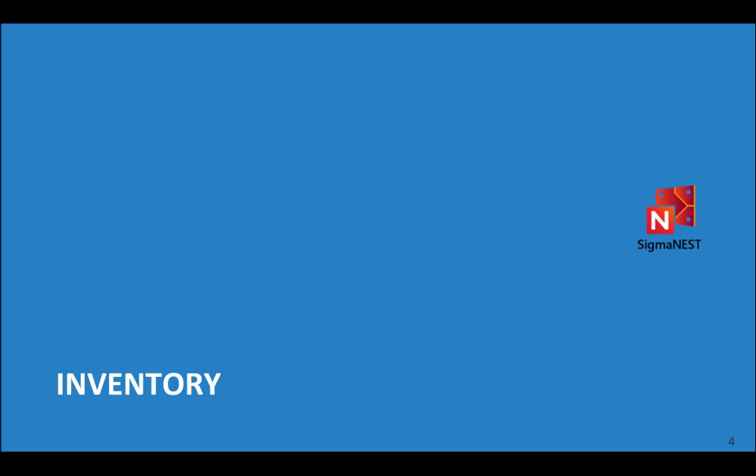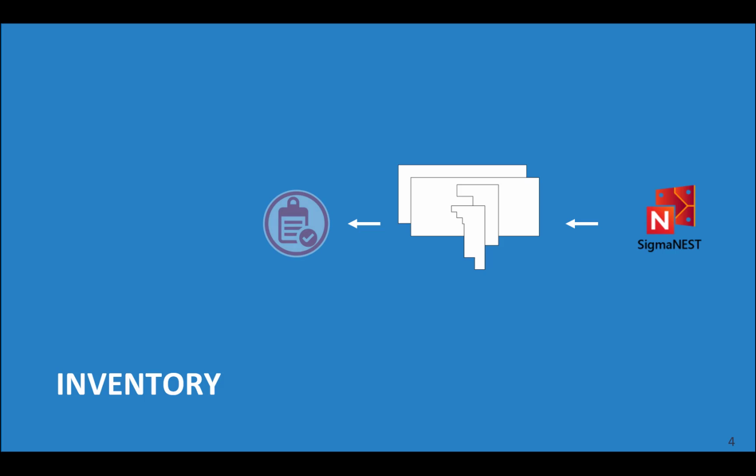So Tekla EPM is meant to be the primary data source for your inventory. So what we do is send inventory updates through SimTrans to SigmaNEST. This can be done from inventory, but typically will be configured as an automated event. Tekla EPM also has a report for SigmaNEST that allows SigmaNEST to send inventory and remnant updates to EPM. This is particularly useful during the setup for remnants that were created outside of the integration.